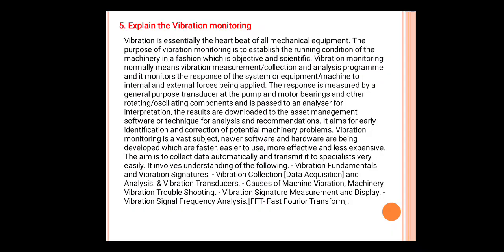The response is measured by a general purpose transducer at the pump and motor bearing and other rotating or oscillating components and is passed to an analyzer for interpretation. The results are downloaded to the asset management software or technique for analysis and recommendations.